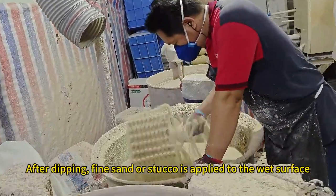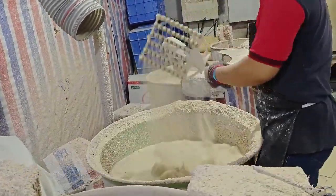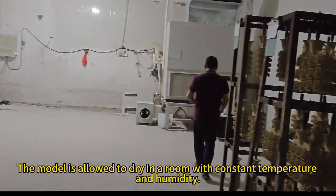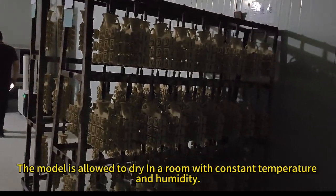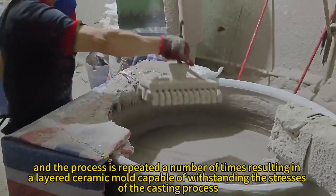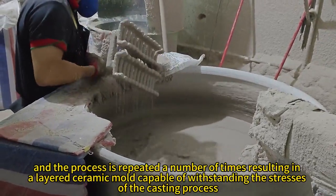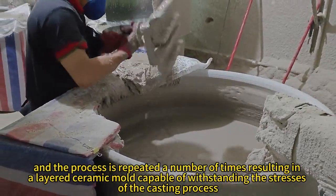After dipping, fine sand or stucco is applied to the wet surface. The model is allowed to dry in a room with constant temperature and humidity, and the process is repeated a number of times, resulting in a layered ceramic mold capable of withstanding the stresses.